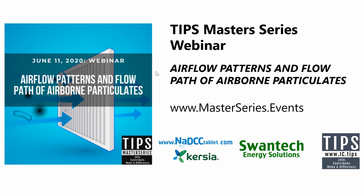I'm afraid I can't give you a generalized recommendation for this. Certainly, people are encouraged to employ these devices and techniques. As I said in my presentation, where is your supply in your room? Where the air is coming in? What type of diffuser is there in your clinic? Is it a slot diffuser or a four-way diffuser? Where is your return? Where the door of your clinic is, whether it is open or closed? All these things will matter, because simply putting a cleaning device in a place is not enough, as I said. So where to place that is also important to understand the airflow patterns.